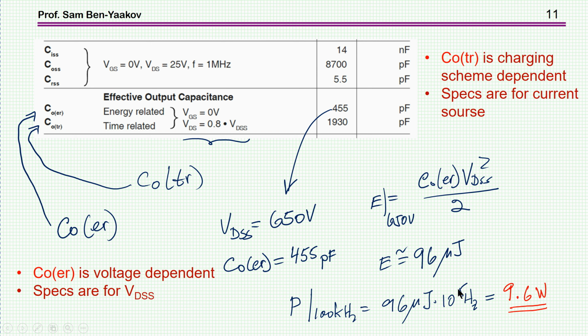So you lose 10%. This is hard switching, okay? We're talking about hard switching. That is, the energy from the capacitor is dumped into the transistor. In soft switching, there is some means that will actually discharge the capacitor without involving the transistor. And thereby you can save this power, part of it at least.